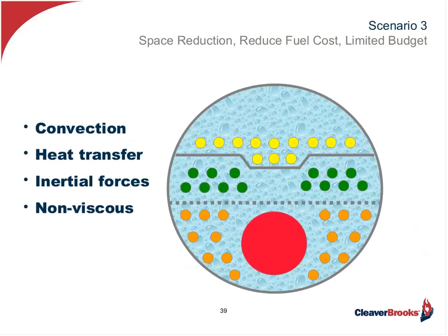The way we designed them before was we would have multiple passes, and we wanted to maintain specific velocities through these tubes. So you've got a plug of gas traveling at about 50 to 60 feet per second down this furnace. We then reduce the cross-sectional area to maintain the 50 to 60 feet per second. We reduce it again and again. So it is through this velocity that we are getting this turbulent flow down these tubes and not laminar flow. But what this did, it added additional horsepower. It added additional geometric size, if you will, to the unit, because we needed 3 or 4 passes to be able to absorb that heat.